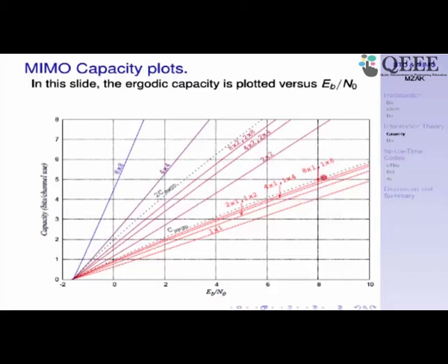See that? But the moment you increase both the transmit and receive antennas, rather than just one, you see the gain here. The capacity has increased a significant amount. For example, at 8 dB signal to noise ratio, SISO, 1 cross 1, has 4 bits per channel use, but MIMO has nearly double. It is more than 7.5. If you go to 10 dB, this would be much higher, because there are two diverging curves, so the gain will increase again.